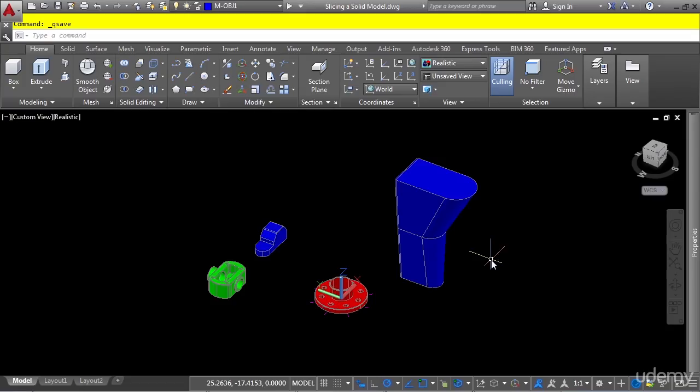The slice command allows you to slice material away from a solid model or to split models into two separate pieces. This capability is especially useful when you want to bevel a model and the tangencies of the model edges prevent the chamfer command from achieving the required results. When you slice a solid model, the resulting face is flat in all cases unless you use the surface option. When you use the surface option, the resulting face matches the surface used to slice the model.